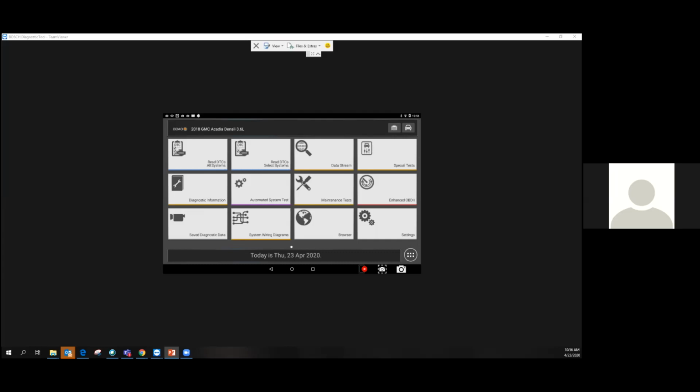The vehicle will be parked stationary, and you're going to be setting up jigs or targets around that vehicle. They may be an optical target, and those targets can look something like a chessboard. It can look like a QR board, and that is placed at very specific distances from the vehicle at very specific heights based on the manufacturer's requirements. Or if it's something like automatic braking or adaptive cruise control, you're going to have a reflector that you have to mount at specific parts around the vehicle. That calibration will be done while it's parked in that bay. Again, you have to put it into learn mode and tell it to learn those positions.